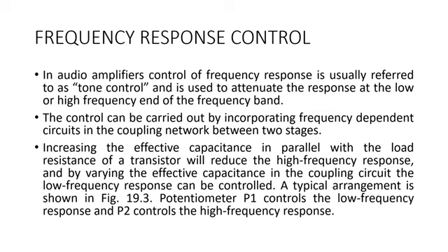Increasing the effective capacitance in parallel with the load resistance of the transistor will reduce the high frequency response. And by varying the effective capacitance in the coupling circuit, the low frequency response can be controlled. These are the two ways I can do it.